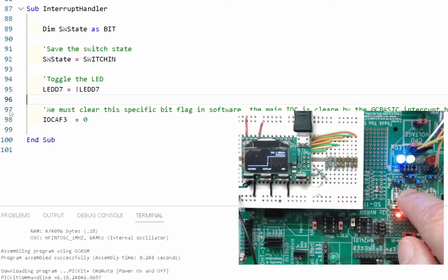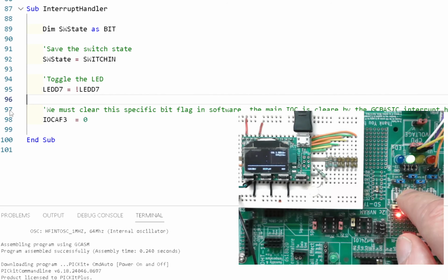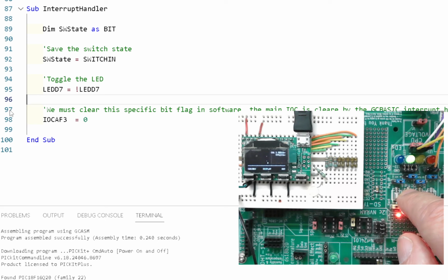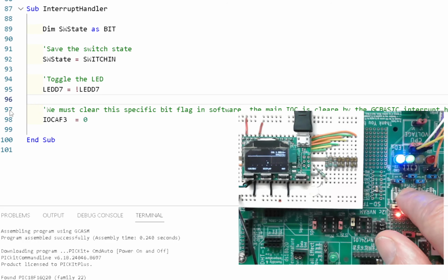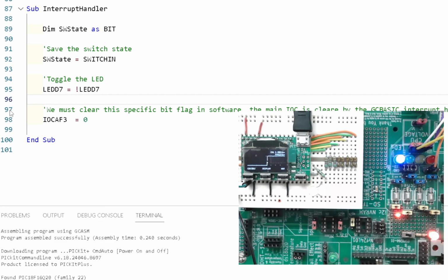You can see that LED 6 is now flashing. That's better. I was being over ambitious with the debounce. So you need to add a proper debounce into there. That's working fine now. That's excellent. So whilst we're here, I just wanted to show you something else on interrupts as well. So that was demonstration 250.